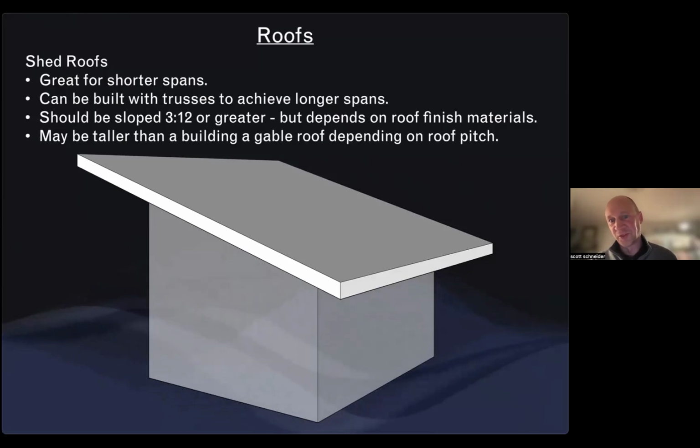When you build a truss, you can have members that are 2x6s, and a 2x6 can span longer than a 2x4. So even the members themselves can determine how long the span is within the truss. And so the trusses can get fairly large.